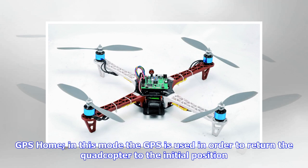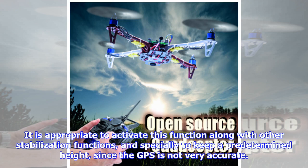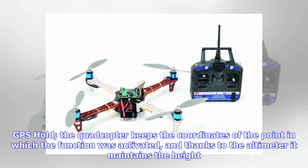GPS home. In this mode the GPS is used in order to return the quadcopter to the initial position. It is appropriate to activate this function along with other stabilization functions, and especially to keep a predetermined height, since the GPS is not very accurate. GPS hold. The quadcopter keeps the coordinates of the point in which the function was activated, and thanks to the altimeter it maintains the height.